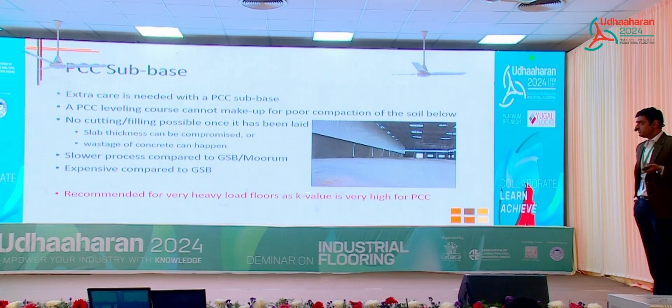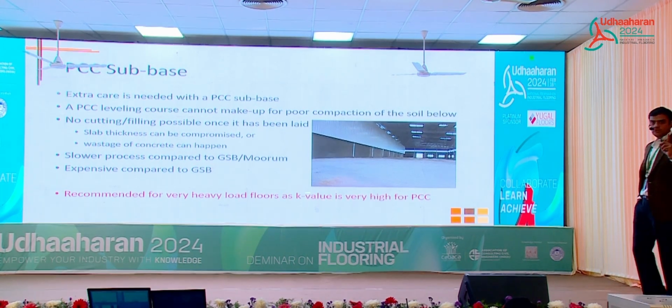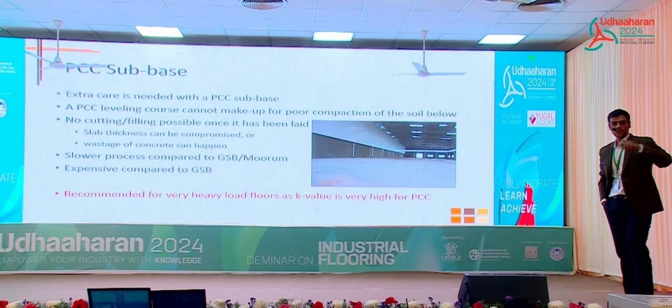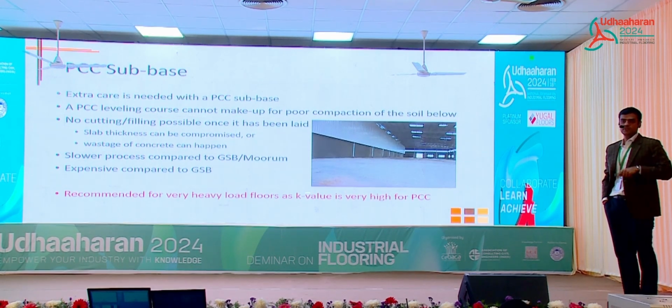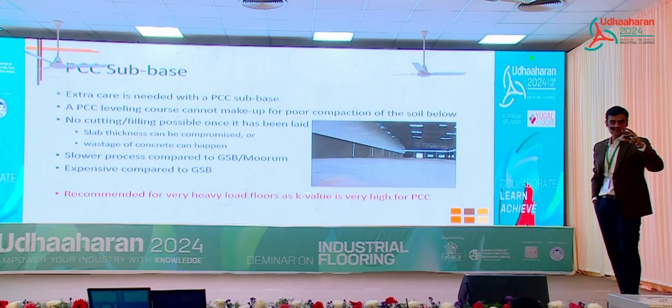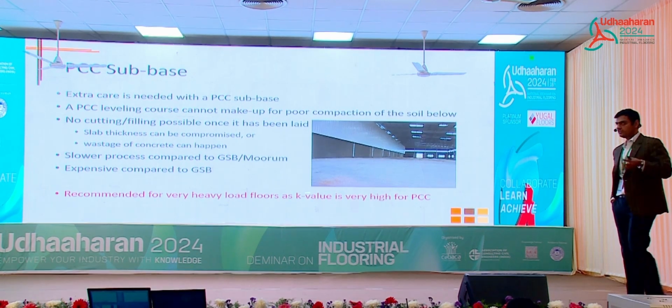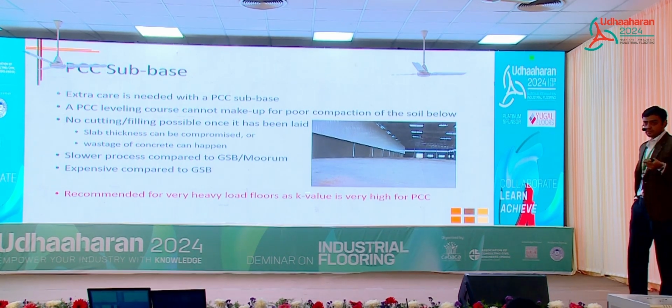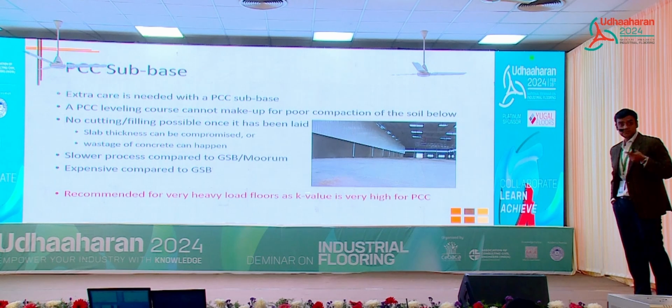Okay, I spoke about PCC. Now, first thing, PCC cannot make up for poor compaction of earthwork. It's like a pigeon closes his eyes when a cat comes, it's the same situation. PCC is not going to save you from poor compaction woes. Biggest disadvantage of PCC is no cutting or filling is possible once it is laid.